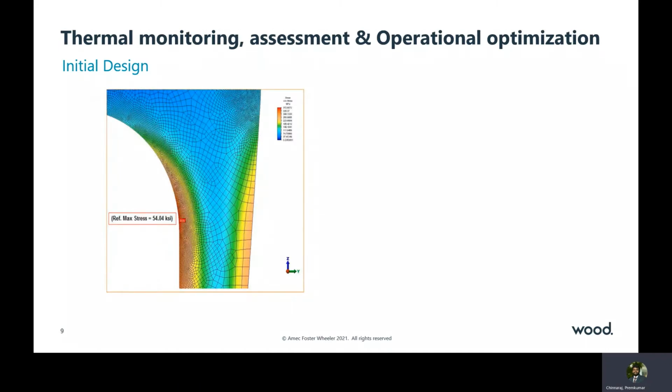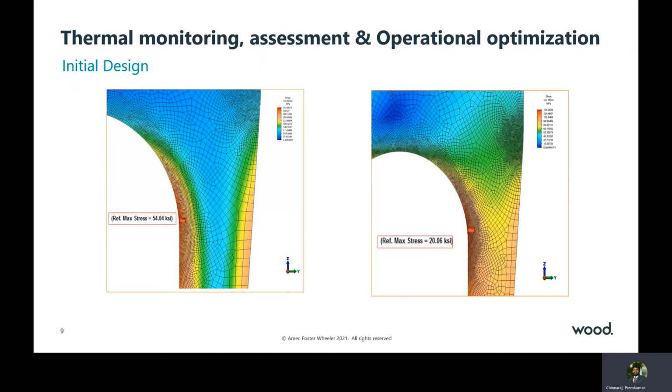This is the FEA plot showing calculated stresses during the design phase. It shows the thermal stresses induced at the inner crotch area during coking. And the plot on the right side corresponds to thermal stresses induced during quench. Then the total equivalent stress range is calculated using stress tensors, which is approximately 86 KSI. Since the forged welding is shop fabricated with no stress risers, a fatigue strength reduction factor of 1 can be used, as described in Table 5.12 of ASME Section VIII Division 2. And the resulting fatigue life estimate during the design phase is approximately 6,500 cycles.